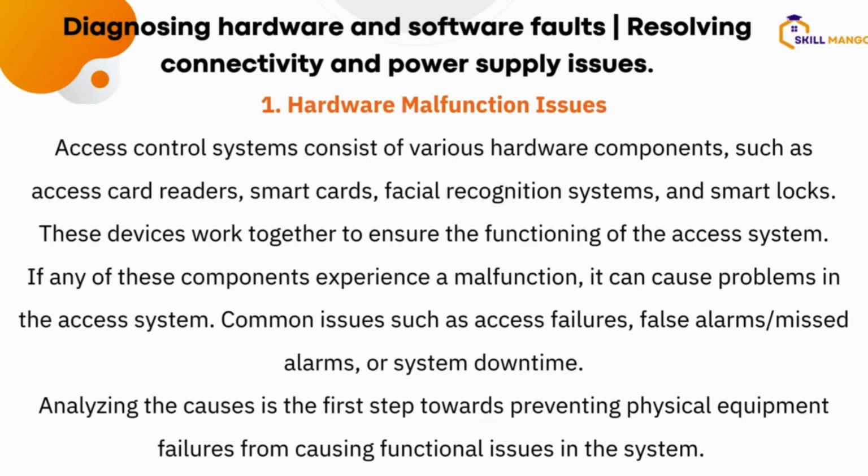You have to understand all your devices' power ratings and power requirements. You have to understand that, okay, your maglock, this is the power rating based on the brand you are using, your exit button, your readers, the kind of cable you use, all the components you are using together, they are reliable and you know their power rating. You now combine all this together. This will now advise you on the kind of power supply to deploy, to avoid hardware malfunctions or problems or issues.